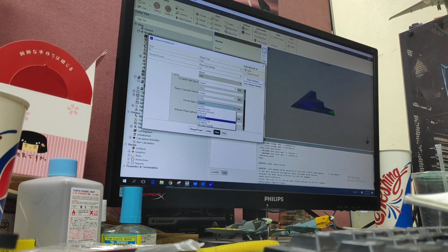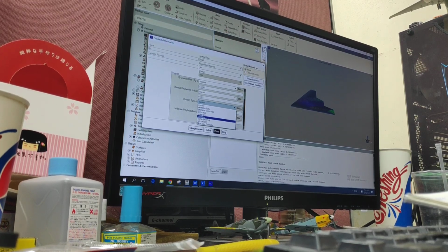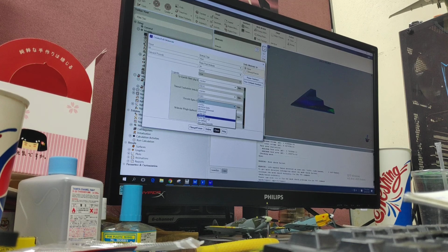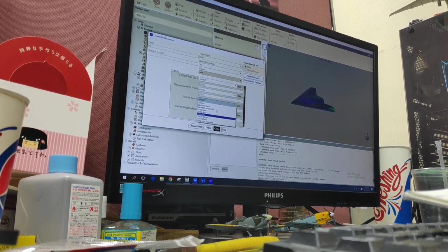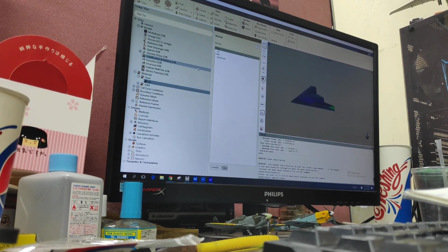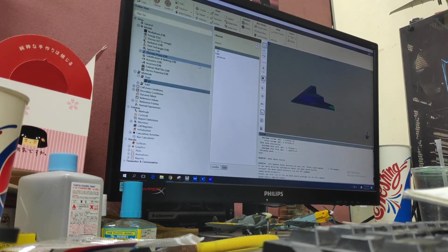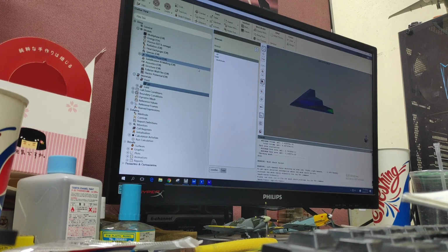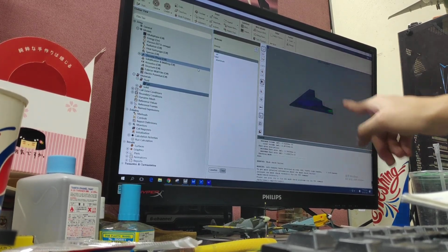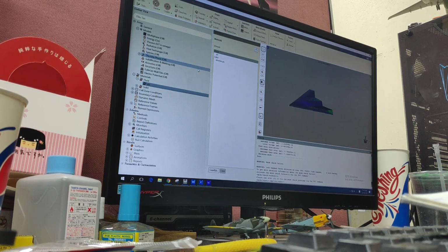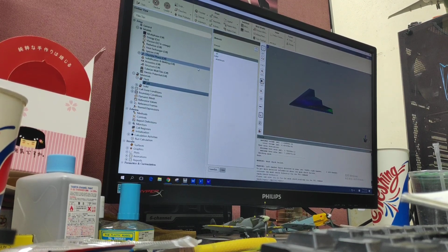Since he's doing some tests in the water, would it make sense to also try tests in the water here, using the same velocity and everything as your test? Or does it make more sense to just have the full size measurements? No, because you say this model is used in a water tunnel, right? So the Reynolds number will be different.